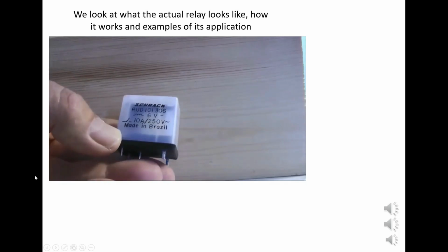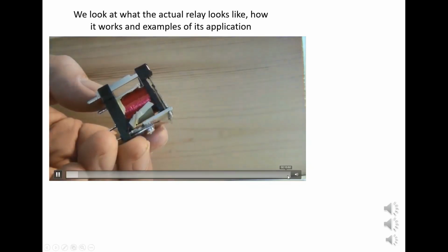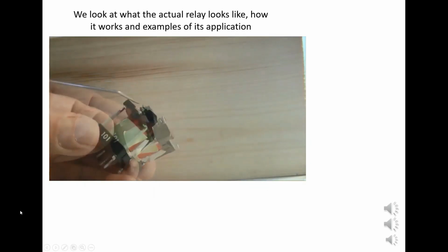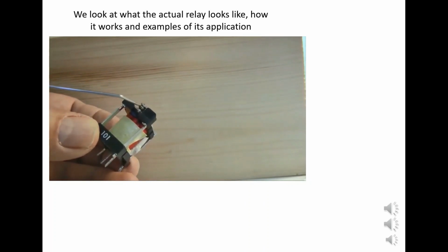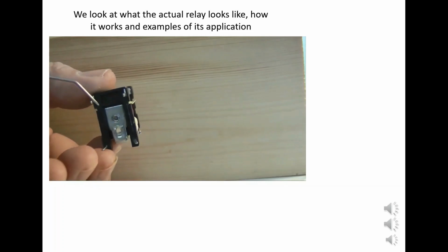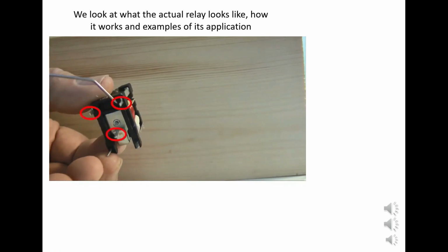It's called a relay, an electromagnetic switch. You can see the fine wire coil in this relay. When the coil is energized, the resulting magnetic field pulls these two contacts together. They are joined to these two connectors. This is where you would connect a circuit. The contacts would switch it off and on.